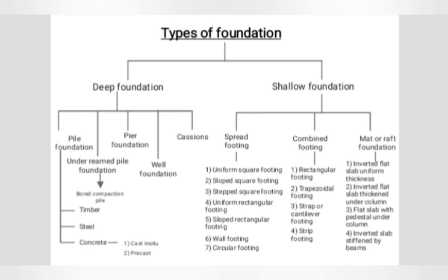Incompressible, water-logged, or made-up type of soil, where bearing capacity of soil is inadequate or steep slopes are encountered, deep foundations are provided for any type of structure.